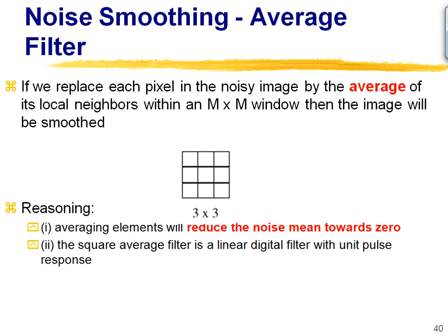So we can think of these properties that we expect from an image, and based on that we can think of doing averaging in order to remove noise, or more specifically get smoothing properties in the space domain. Right? So I can take a small set of pixels and average all of them, and just like we've done with windowed operations in the past, I can alter the pixel value at the center of this region.